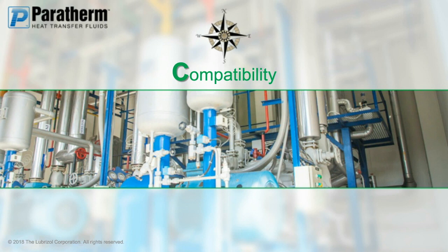So having that conversation of what the previous fluid was and the procedure in which you're removing that fluid, having that conversation with your potential supplier is going to be key in determining compatibility with the new fluid you're putting in. And what are the issues with that? Well, miscibility is one key issue. If the two fluids are not able to fully mix together, you're going to have phase separation. Phase separation can cause all kinds of problems with vaporization of one fluid over the other, pump cavitations, unnecessary wear on the gaskets and polymers throughout the system itself.